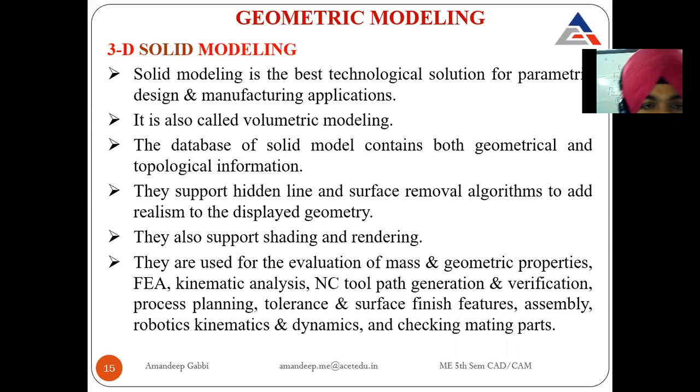So these are some of the figures related to surface modeling. Then 3D solid modeling. Solid modeling is the best technology solution for parametric design and manufacturing applications. The initial one was the wireframe model, in which you join lines to form a surface. It looks like a body, but it is actually empty and generated from lines only.